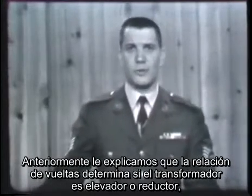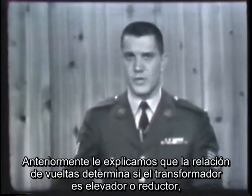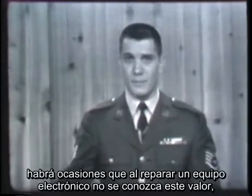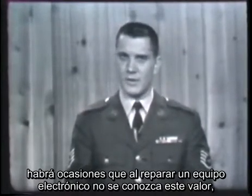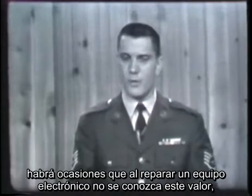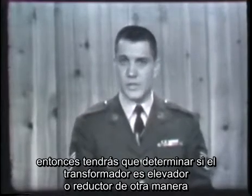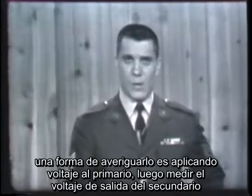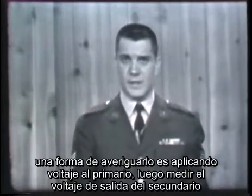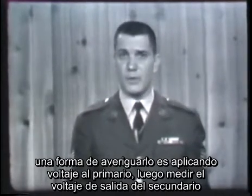Now, earlier you learned that the turns ratio of a transformer determines whether the voltage is stepped up or stepped down, and by what amount. There will be times when you're troubleshooting electronic equipment, however, that the turns ratio of a particular transformer won't be given. Thus, you'll have to determine whether the transformer is a step-up or step-down transformer by other means. Now, one way to readily determine this is simply by applying voltage to the primary winding and then measuring the output voltage of the secondary winding.